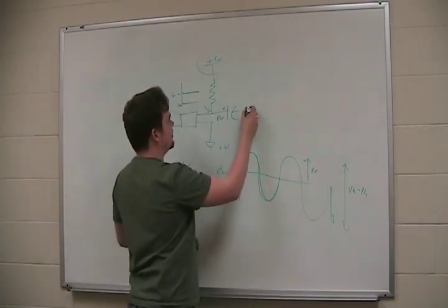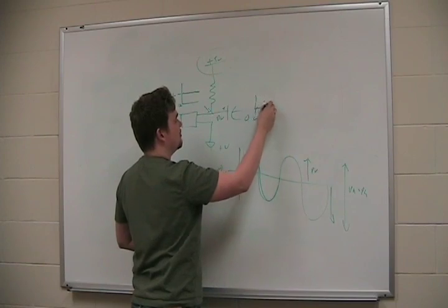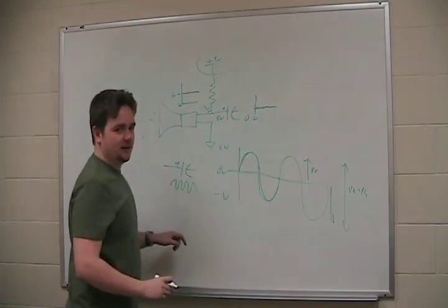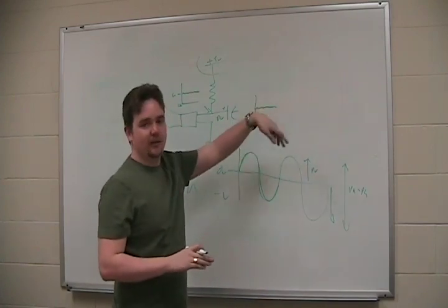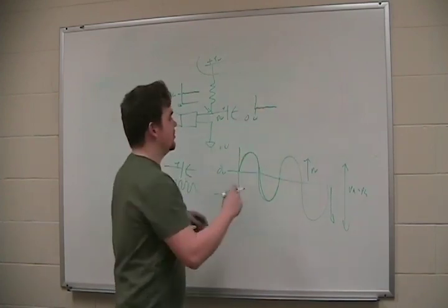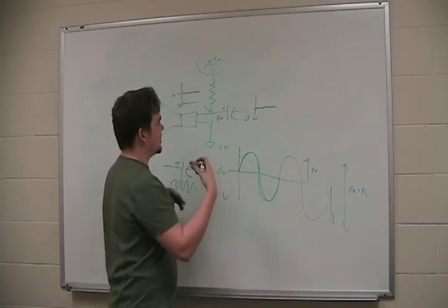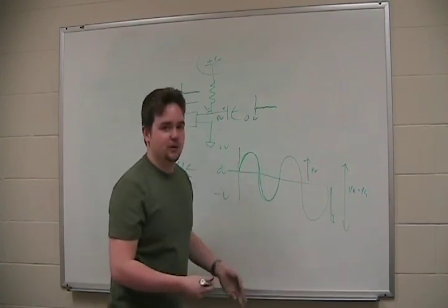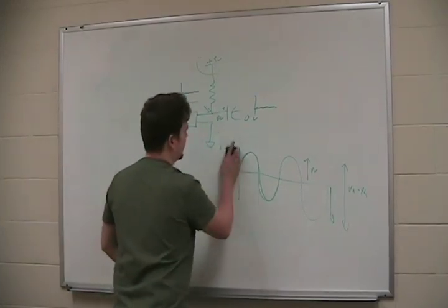But what we're going to see here is just the AC component created from it. That's great because we can amplify that signal and get a beautiful AC signal from that using certain amplifiers, which of course we'll get into later. But that's one of the reasons why we use capacitors. We also use capacitors for filtering.